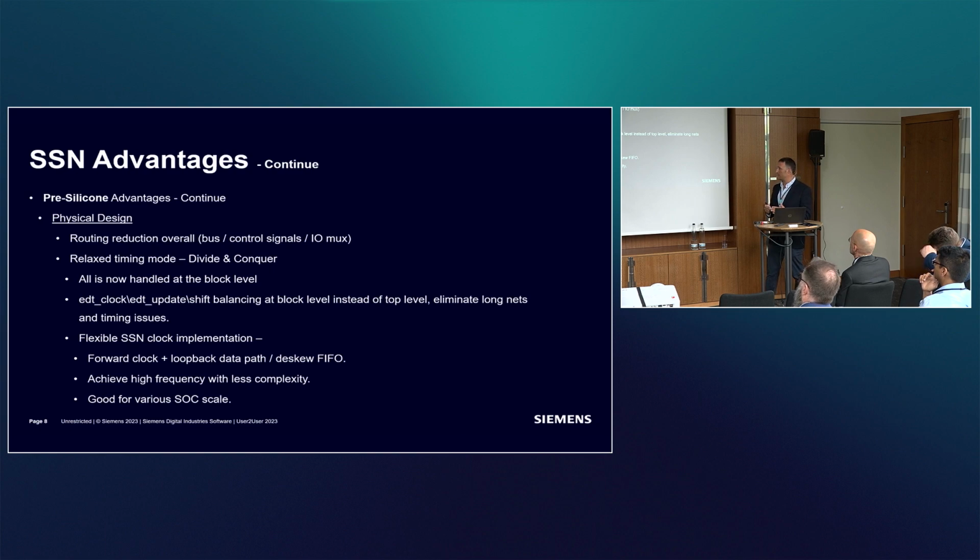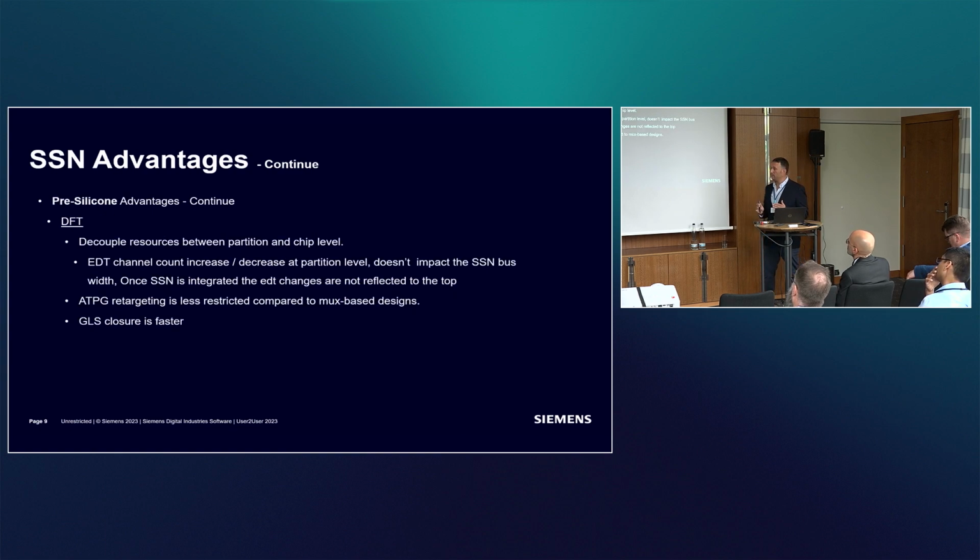Much easier for them. And the forward clock, although it's a very good solution and a very good method for us, has some limitations if we have a complex SoC with a lot of instantiated modules. It's not that easy to keep up the forward clock methodology, but in most cases we could do that. So everywhere we could do the forward clock, we kept that idea.